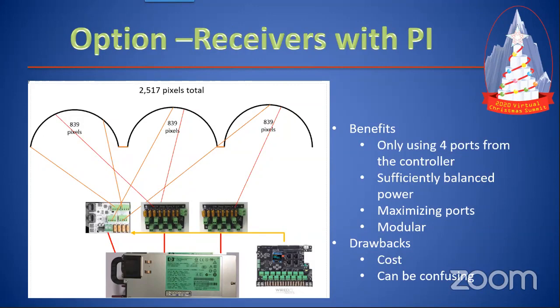And then, should power supply chassis grounds be tied? I mean, you can. There's no reason why you can't. But your grounds are already tied when you're connecting all your equipment, so you don't really need to.